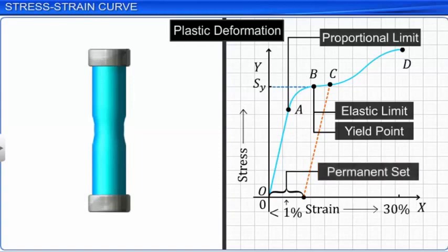At a point where there is a defect or weakness, all further plastic deformation is concentrated in this region, and the material begins to neck or thin locally. Because the area of cross-section now decreases very rapidly at the neck, the effective load at this point decreases, and so stress reduces till the material actually breaks or fractures at this point. The break point or fracture point is represented by point E on the graph.